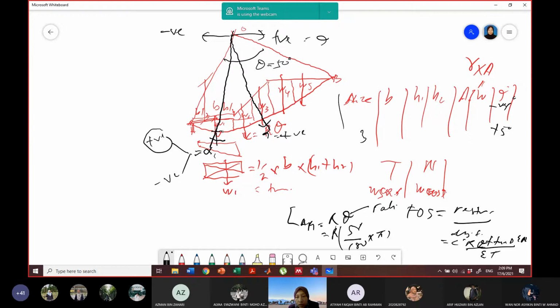One more thing is that when you calculate the formula of FOS, please make sure that you are using the right one, whether you have the ESA, effective stress analysis, or the total stress analysis. Both analyses are done using the method of slices, because in your syllabus we only covered method of slices. We also have other methods, but they will not be assessed in your syllabus.